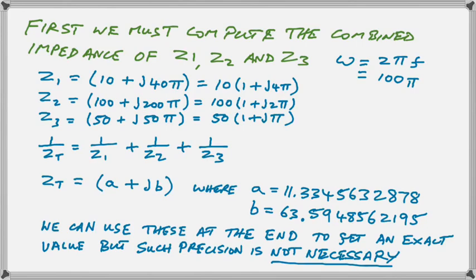Now, the formula that we use for the imaginary part of the complex number is simply omega L, which is the inductance, and omega is 2 pi F. So basically, we've come up with those complex numbers by simply putting the resistance as the real part and the inductance multiplied by 2 pi F. Remember, F is 50 hertz, so it's actually 2 times 50, which is just 100 pi, times the inductance, and that gives us those complex numbers.